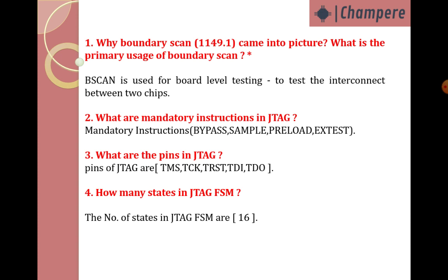JTAG pins are TMS test mode select, TCK test clock, TRST test reset, TDI test data input, TDO test data output. These are the pins of JTAG, or the pins of the TAP controller. Sometimes they ask what are the pins of the TAP controller, and we can say these pins, right?